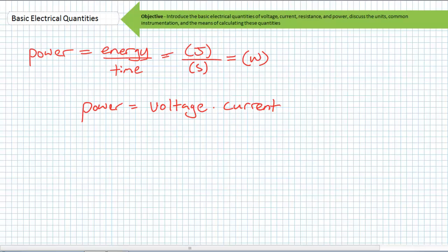The unit of volts is a measure of potential energy difference between 2 points. It's actually a derived unit where 1 volt equals 1 joule of energy per coulomb of charge. A coulomb is a means of packing up charges into more usable numbers. Kind of like a dozen eggs actually means 12 eggs. Except a coulomb is a lot more than a dozen electrons. It is a lot more. The unit of amps is a measure of the amount of moving charges in a given time period. It is also a derived unit, where 1 amp equals a quantity of 1 coulomb of charges moving by in 1 second.